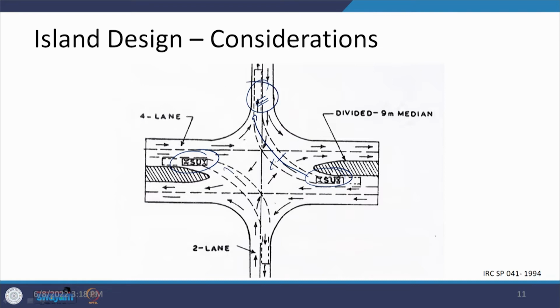Similarly, when it is going to take a turn here, then it goes clear of it and it remains in the lane in which it is supposed to go. So, this segregation is also there of these two movements, and the through traffic is moving continuously here. So, there can be a conflict here, there can be a conflict here, but the other conflict is not there. But at the same time, if the traffic coming from here goes, then there is this conflict. So, this is a smaller area here and a smaller area here, which may have these conflicts,